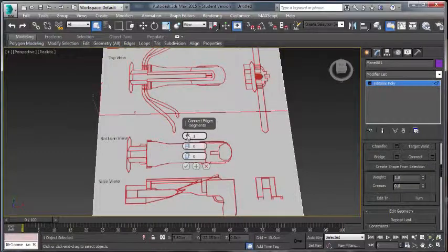So we'll just reset that. I'll just right click to reset it back to 1. This middle one here moves or pinches how many. So if I have 2 edges that I want to create and I want to move them away from each other or pinch them together, then that one does that as well. So I'll just put that back to 1, and this one just shifts the edge down. So this is the one that we want to use at the moment.